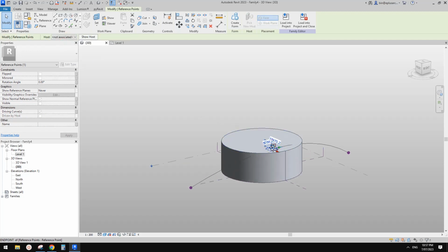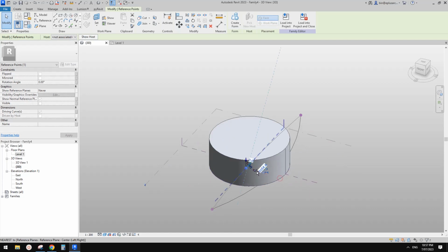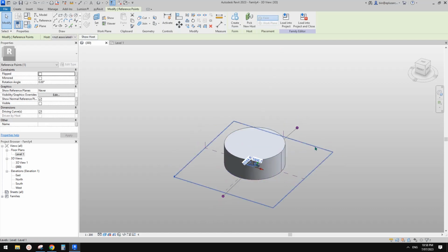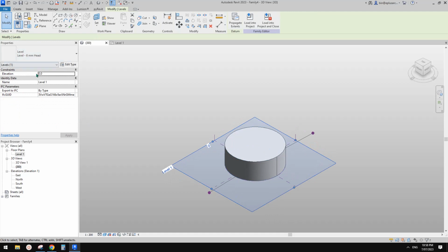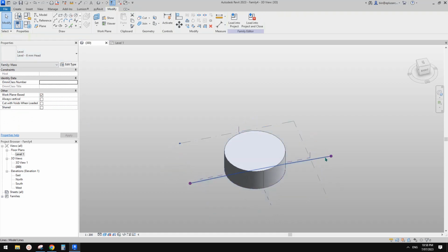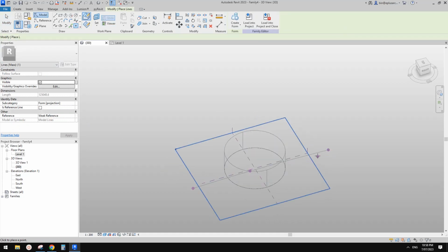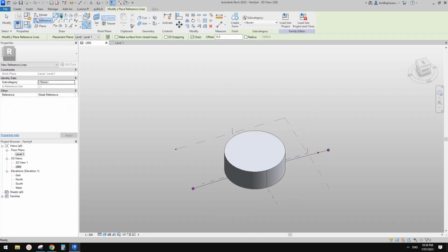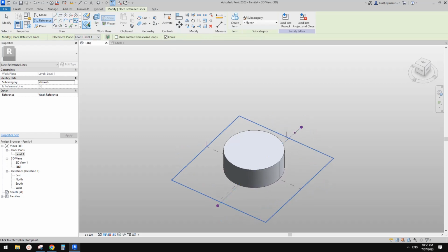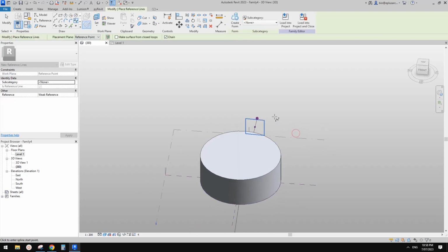I just want this one to be on level 1. What's that called? Level 1. Yeah, and then I'm going to place a point and then create a shape. Okay, so maybe I'll just use spline. Okay, so draw on work plane, set work plane. So I create something, organic shape.